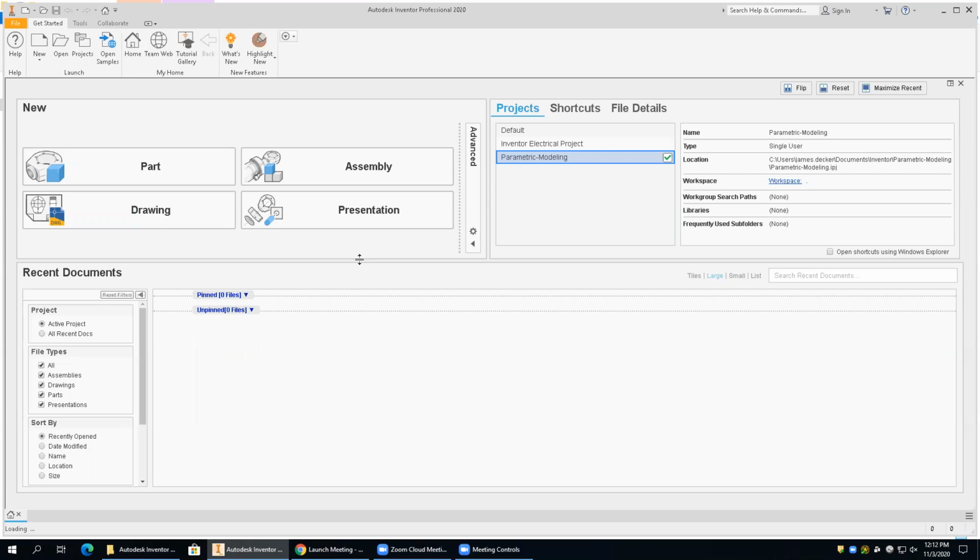Everybody? Okay. So Inventor, unlike CAD, is a parametric modeling kind of guy. So it's a bit different. First off, it's dealing with what we call solid modeling. It also is parametric, which means that something here can drive something else that can drive something else. They're all linked. So in CAD, when we're drawing, a line is very static. That line knows how long it is, and it knows its two endpoint coordinates, but it doesn't really know that it's connected to anything else or how it interacts with anything else other than what you tell it to do. With Inventor, what we're going to see is that these things are linked together, and that one thing can drive the other.